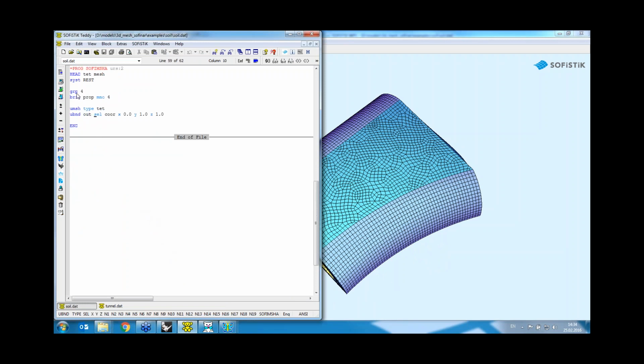We're defining a group number brick properties for this tetrahedral mesh, and we enter UMesh command, type of element tetrahedral element. We will let at this time the software to define the maximum element size and the progression factor, even though we're able to also manually define it.